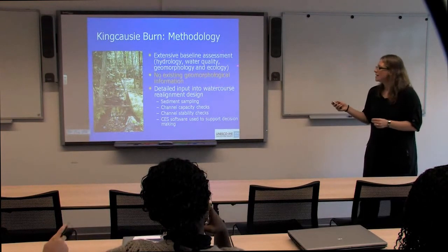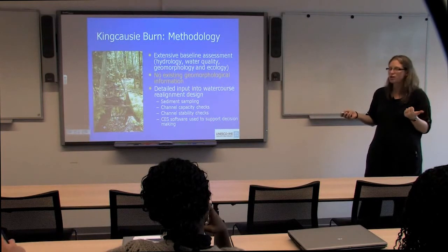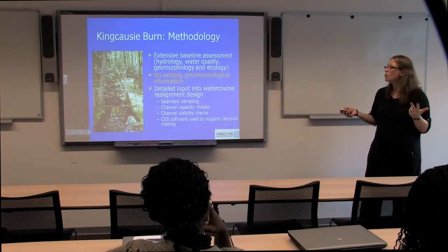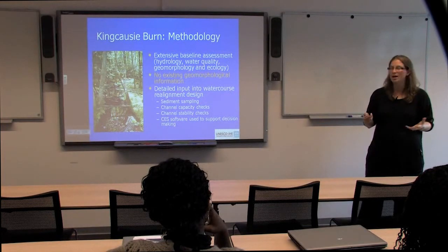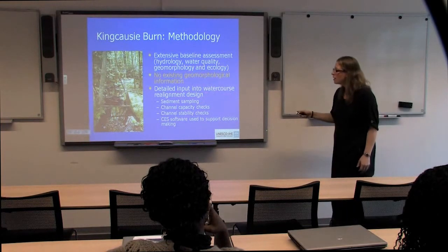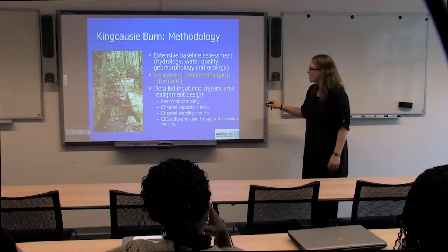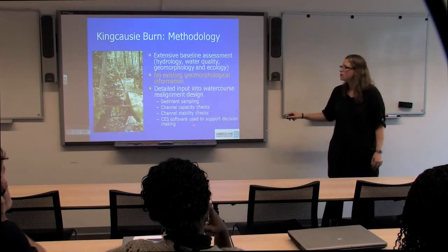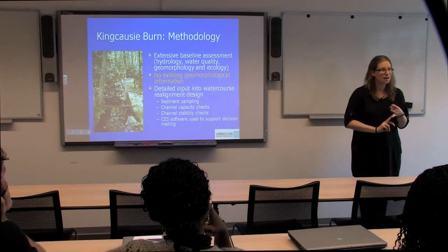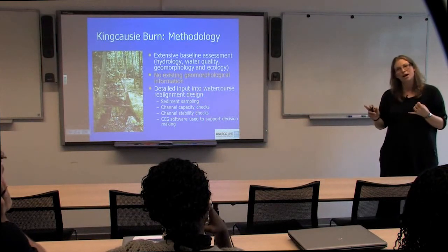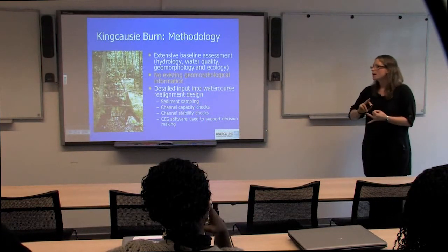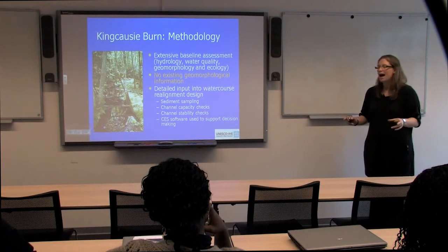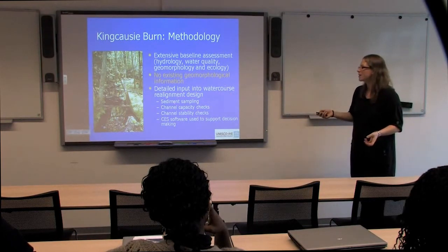So we had an extensive baseline assessment. We looked at the hydrology, the hydraulics, water quality, geomorphology and ecology. So we had the different experts in. And what we went out to do was also sediment sampling, and we'll have a look at that this afternoon. Channel capacity checks and channel stability checks.